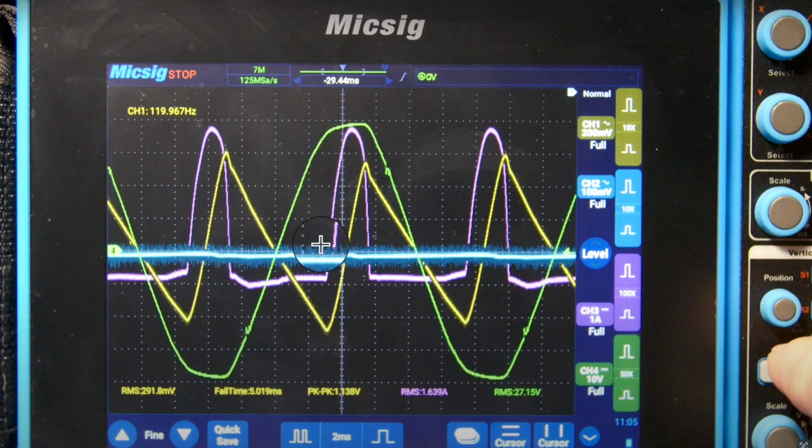But also this yellow one is the voltage of the ripple waveform on top of the voltage. It's AC coupled, so we're just seeing the ripple part. What we see is when this purple pulse goes up here on the left, the yellow ramps up. From right here, the pulse goes up, and we see a nice linear ramp because the current's going up. It's almost linear, right? It's almost a straight line. So the yellow one climbs up, charges up, and then right here where it starts to drop, it drops too.